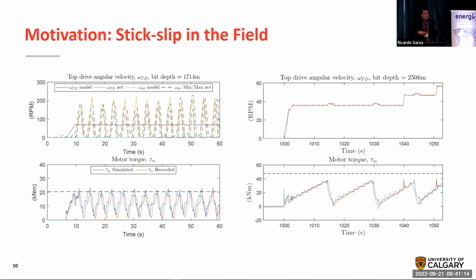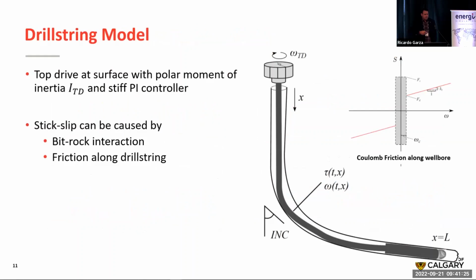So what's happening for these two scenarios? Very similar wells, very similar overall operations, different physical manifestation. It was a deviated wellbore. You can have a nonlinear friction or a sticking force occur either at the drill bit or along the drill string itself, so along the drill pipe. And what we saw in these wells is the stick slip started before you started drilling. You're off bottom, you're not making hole, you start rotating and you're sticking to the side of the hole. You get on bottom, it gets even worse.